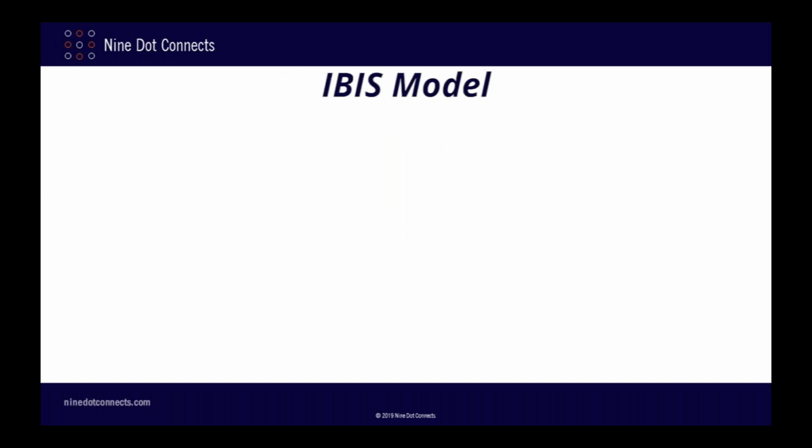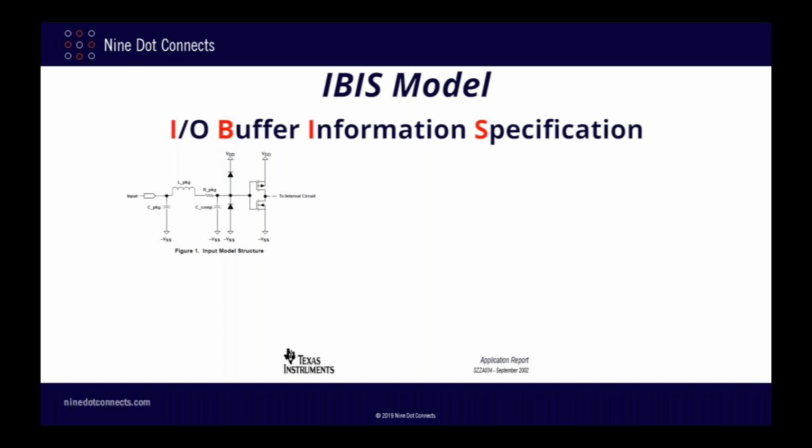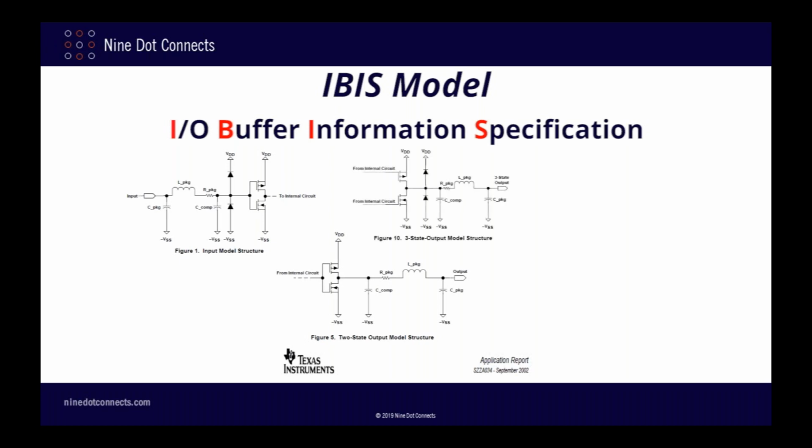At this level of simulation, the behavior of the controller is described by something called an IBIS model. IBIS, which stands for I/O Buffer Information Specification, is a means of allowing us to simulate the operation of the device right at its pins without needing to know any proprietary information about what goes on inside of the chip. IBIS essentially just describes the electrical operation of the pins themselves and leaves it up to the simulator to handle the wiggle the bits part, as it were.